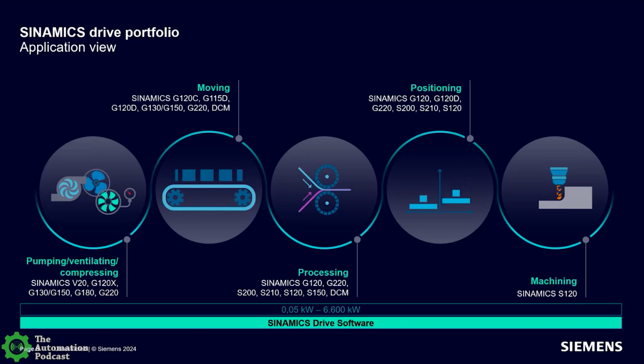Any other thoughts there? Yeah, when I got started in '90, everything was about energy savings. VFDs can save you just a ton of energy. I mean, it is amazing. If you want to save electricity and you haven't looked at this, it has always been VFD versus across the line. There's also some specialty applications too, like water knocking inside of pipes, pipe knocking.